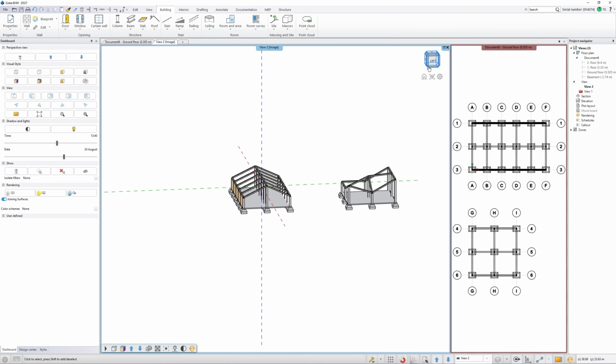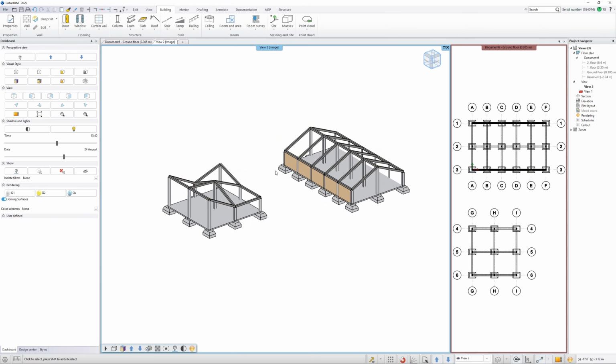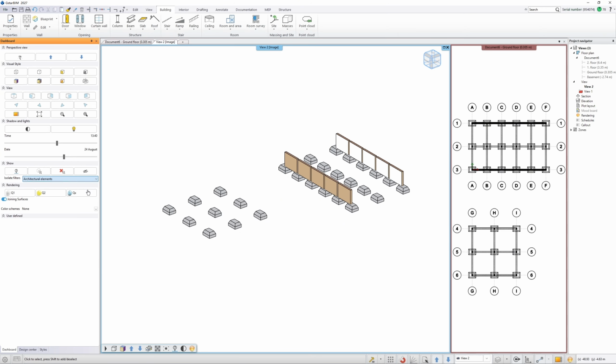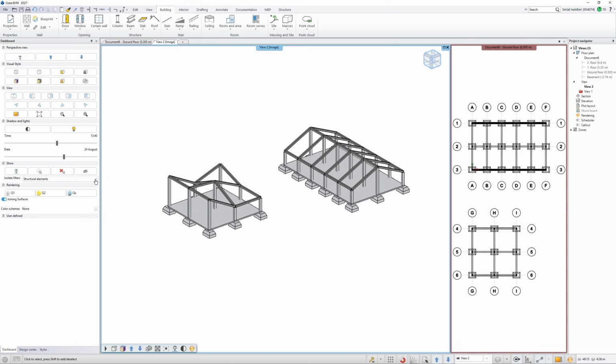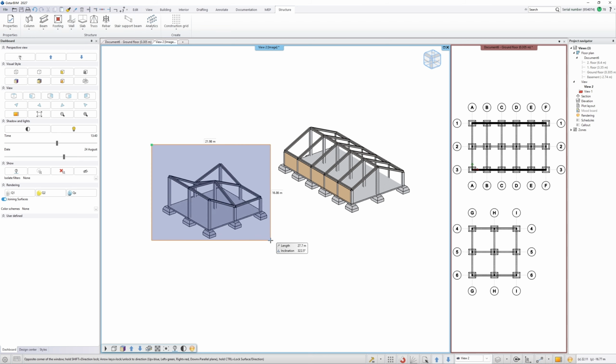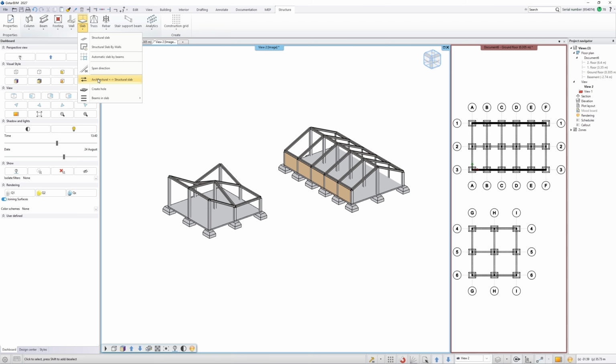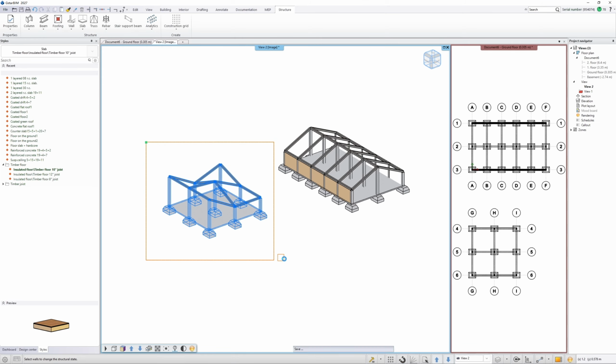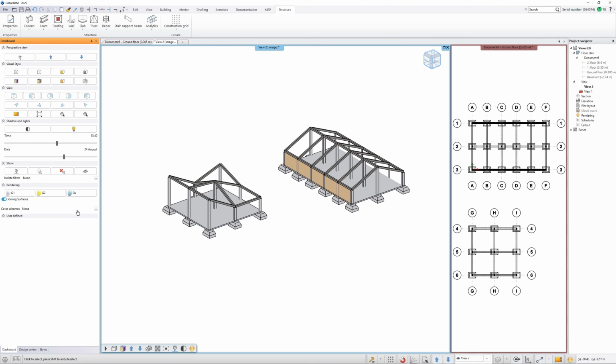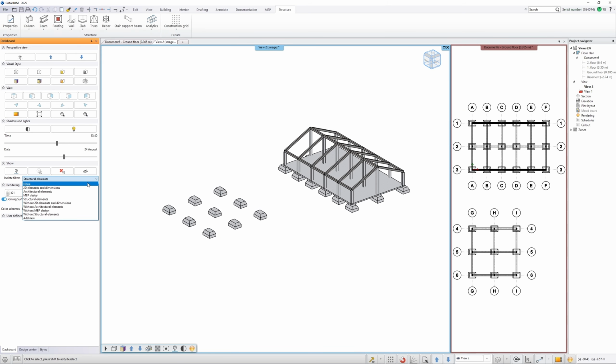In our model, we can switch between displaying architectural and structural elements with a single click. If we want to change the type of a given element, we can do so with a single click. This feature is very useful when we have already placed an element during the design process, set all its properties, but need to change its type. By selecting the element, the modification is made immediately, so the filters display the status corresponding to the new setting.